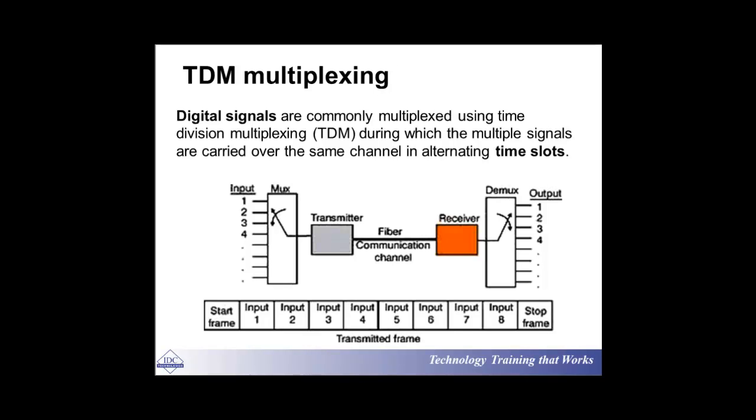So all I'm saying is that in your 61850 automation system, you have already selected a number of signals to be picked up and analyzed, transmitted to the other party, analyzed again, and then sent back to the RTU or PLC or whatever you have in there, right? In order to do that, you need a communication channel in between. Whenever you have a large array of information to be sent to, let's say, the SCADA master station, they have to be multiplexed. That multiplexing could be based on frequency, or it could be based on time.